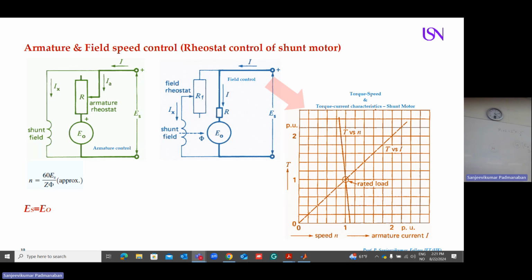So in the speed torque characteristic at the beginning of your shunt machine, the torque rises more than 200% because your current rises to 200%. Then I'm going to look at the characteristics between current and torque. Look at the characteristics. Why does the torque go high? You see, it increases steeply. They are linearly proportional. That's why in the beginning, the machine takes a large current and will produce a large torque. After a fraction of a second, it comes to the normal position.